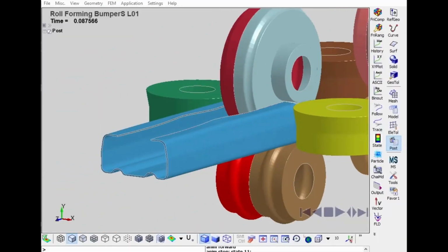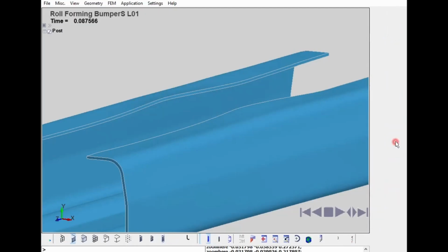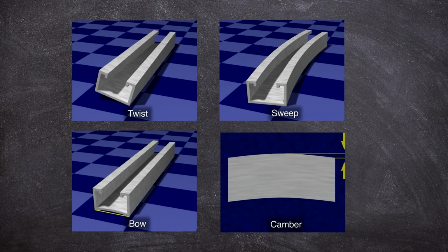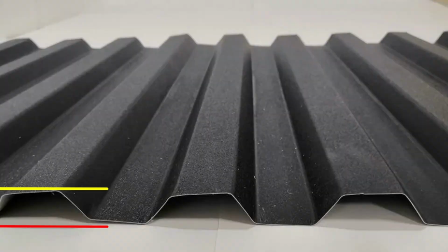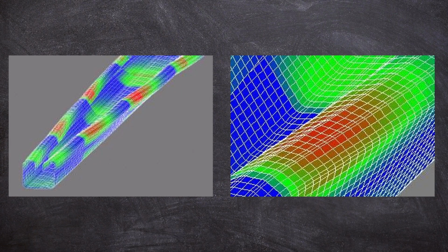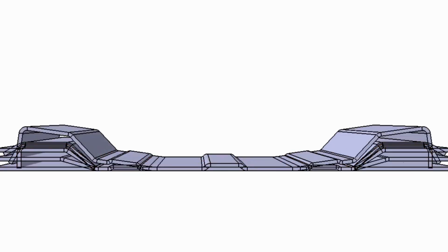There are programs for calculating profiling that, based on a mathematical model, can show the best profiling option as well as places of high stress concentration, due to which rolling defects can form. For example, the profile can go like a screw, bend like an arc, a sickle or a bulge can form. Or the profile shelves that are parallel in the drawing may in fact be somewhat non-parallel. And seeing such places with excess stress, the designer must take countermeasures in order to get high-quality rolling. Automatic creation of the flower pattern scheme significantly speeds up the design of roller tools for repetitive profile types.